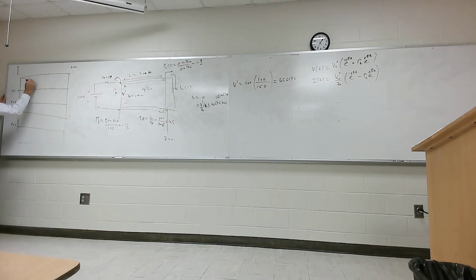Now, at t equals 0, this is the voltage bounce side. Come down here, I've got V prime coming here, which is 66.667 volts, right? Coming back here, I'm going to have minus 66.667 volts, correct? Here, this times, can somebody give this to me, times minus 1/3. That's 22.22 something volts, isn't it? Coming this way? Yes. 22.22 volts.